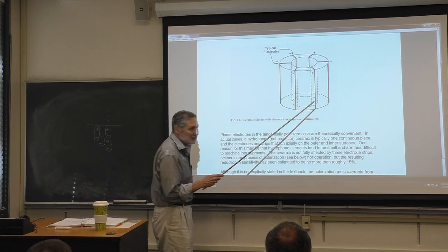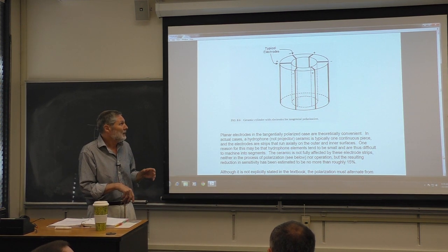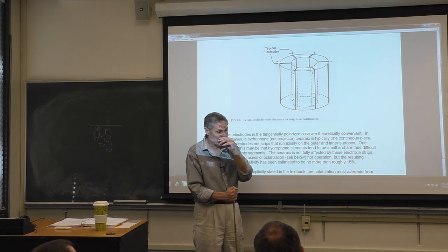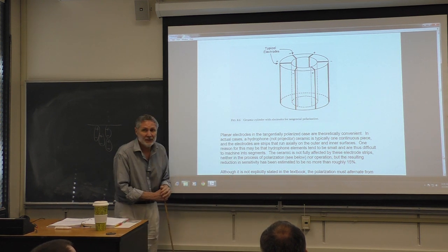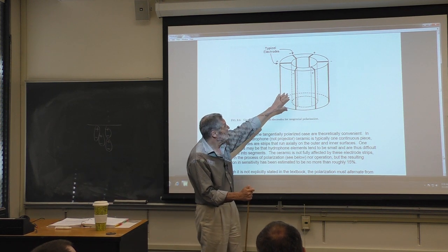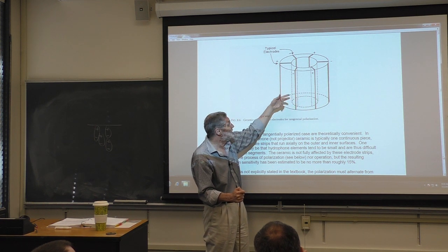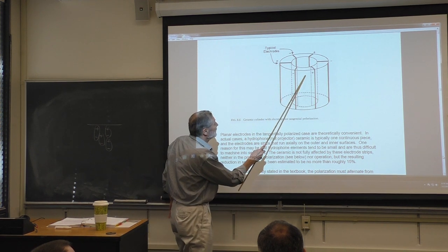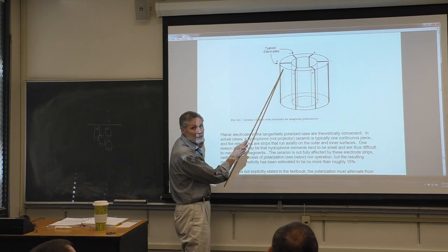will look like this. I think we've talked about this before, but this is very appropriate now to get into a little bit more depth. This is going to be PZT, usually. Not always, okay? But usually it's PZT. And in the construction, I think what they do is, if you construct this without it being polarized, and then you zap it with a very large DC field. And what effect is that going to have? Well, here it's going to polarize this material this way, right? Over here, the opposite way.